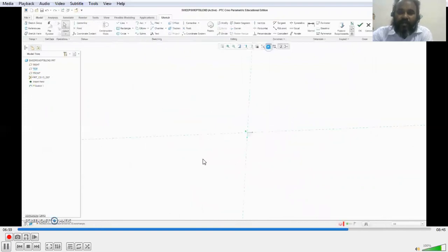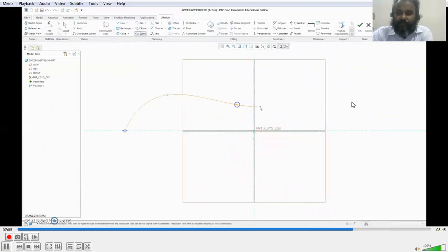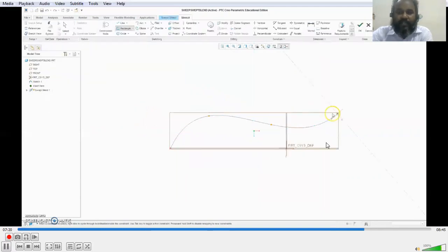I'm taking a spline and choosing the sketch plane, so that I can draw the spline. And what I'm going to do is create two different sections on the ends of the spline, and we'll follow the same procedure and see what the output is. Here's the spline, and I'm going to create the plane, a rectangle here and a circle here. I think the video is a little slower. Kindly understand, nothing else I did. Whatever I followed before, I'm just going to follow here.